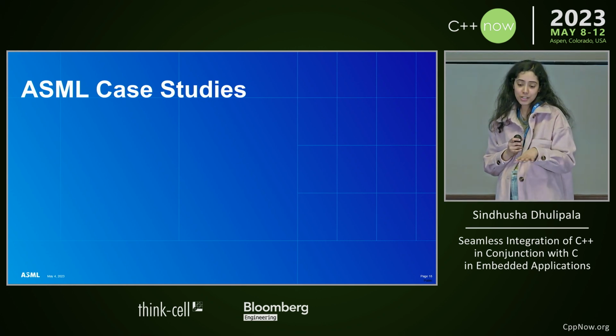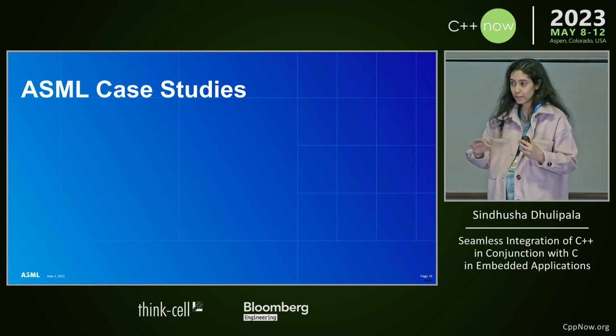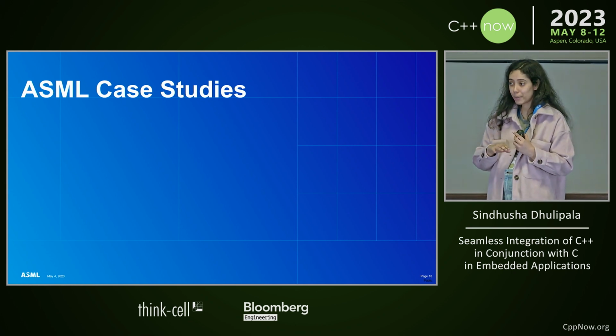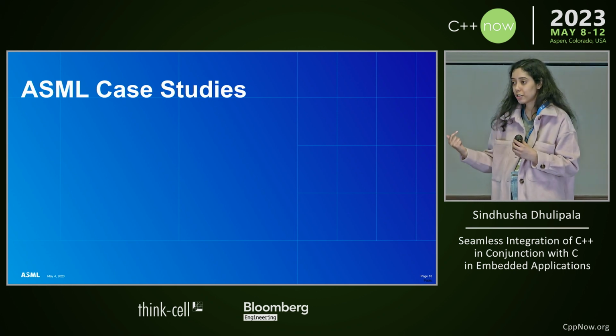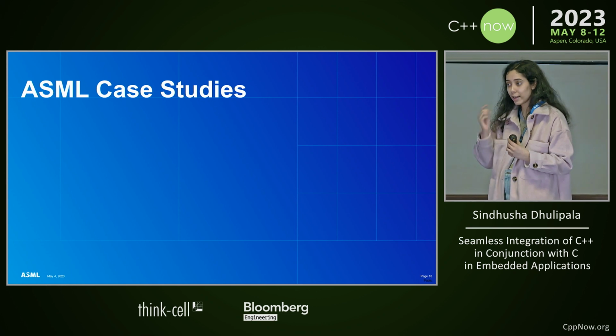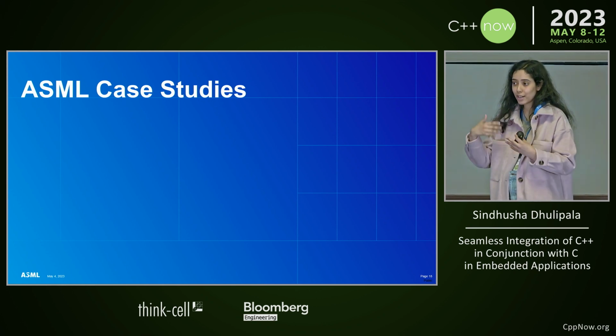Well, I don't necessarily mean ROM, but more like in some of my applications, I've had to take the status of the machine and write the status onto the ROM on a regular basis, so that if the system crashes, I'm not starting from the basic. I can pick up where it is, because it would take time to reach that stage again. It's just time consuming to start an embedded system from scratch. So we want to have a backup of things.